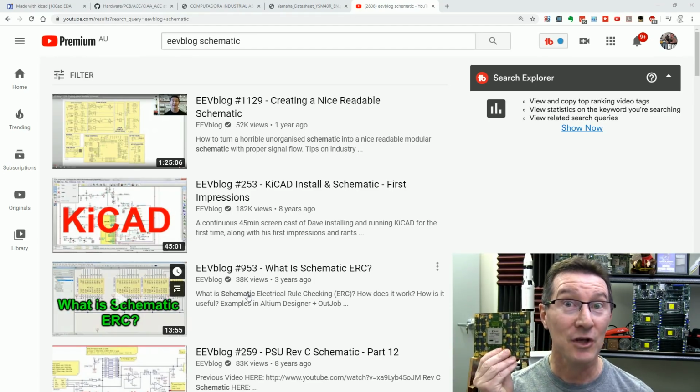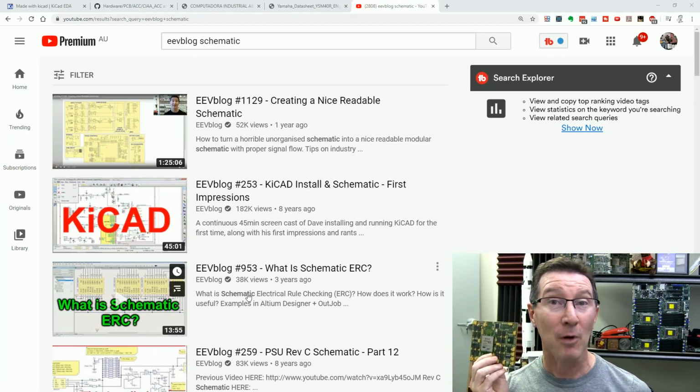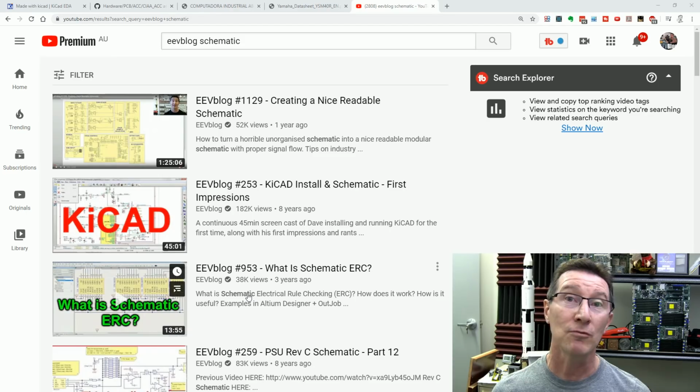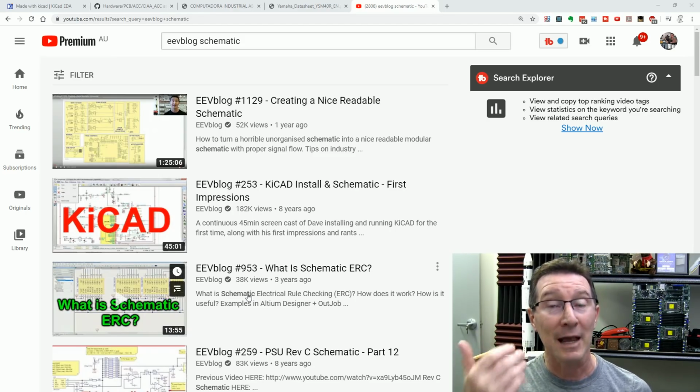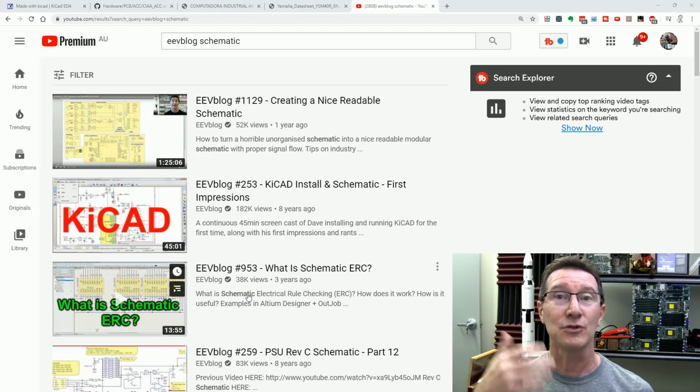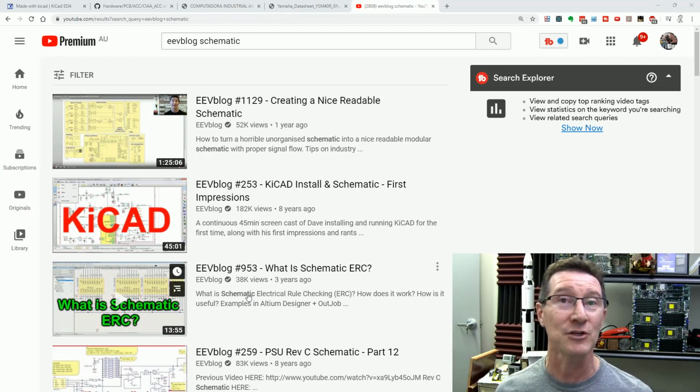So designing your widget like this is a multi-step process. Typically, you'll design your schematic first, and then you'll do your electrical rules test in your ERC, then you'll lay out your PCB and do your design rules check, and then you'll generate the manufacturing files for it, and then you typically get it assembled and everything else.